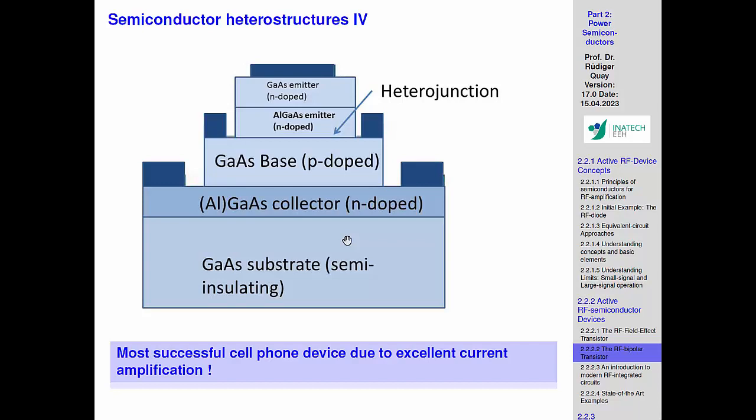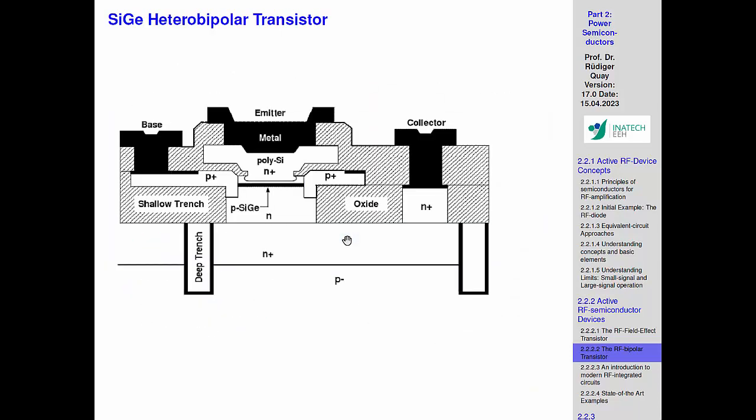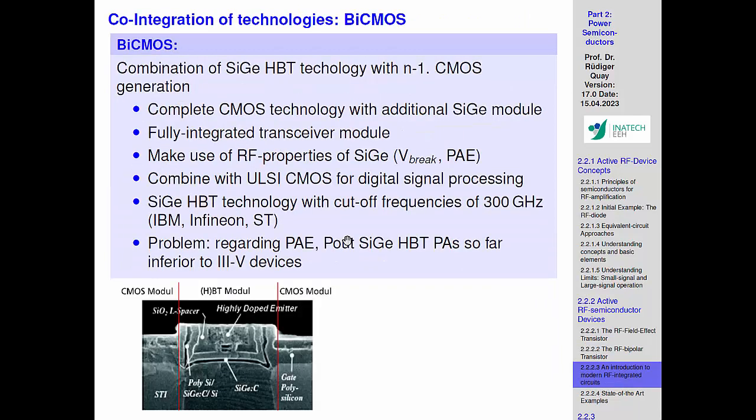So it's just to give you the first flavors. The race is open, and there is not the better one, and this is the smart move actually of silicon and germanium heterobipolar. You use both. So this BiCMOS I was talking about is really the smart move because you take the best of both worlds. For digital, CMOS is clearly better, and for the RF part, bipolar for power is better, so you can do that. And you see it here, so it's fractions of the wafer.